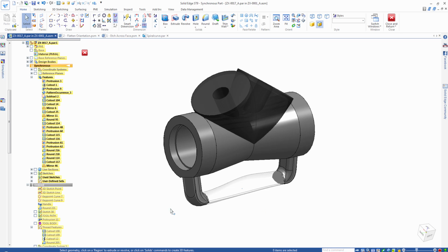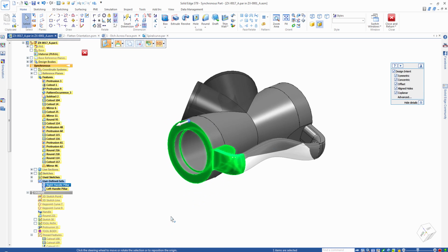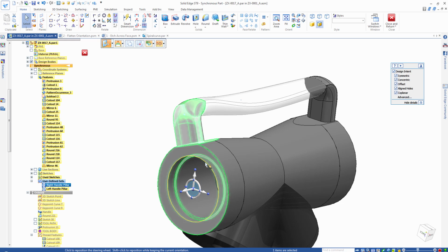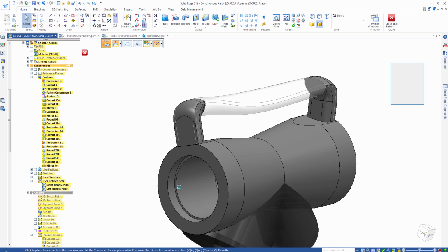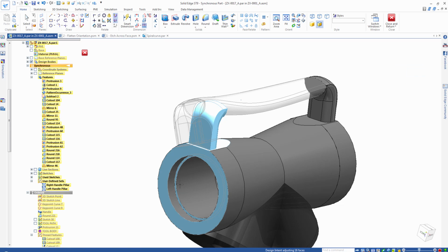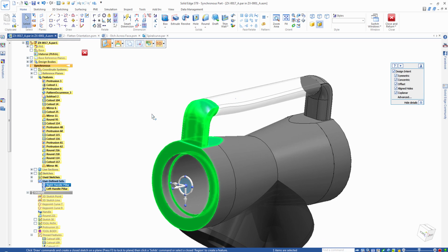So what I want to do is come down here and select this component, and I'm actually going to just flip this around so it's a little easier to see. We're going to rotate that. So I'm going to move my steering wheel to the center point here, and we're going to rotate that about 20 degrees. You'll notice once I place that, our handle will update to match those changes, and it'll recalculate the ordered part on top of that synchronous change.